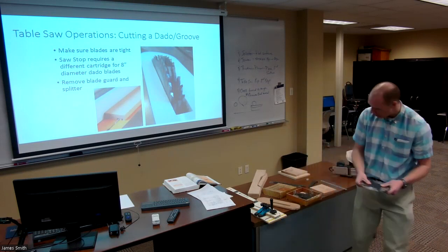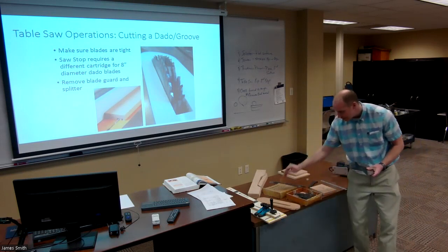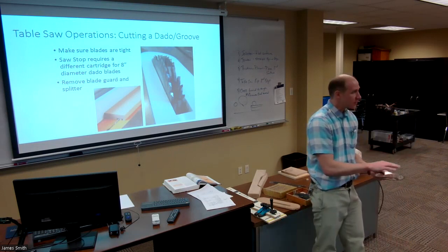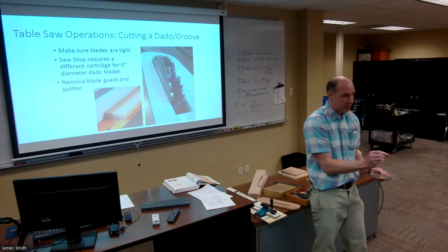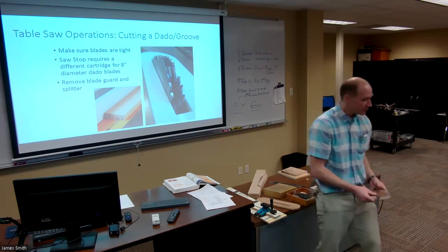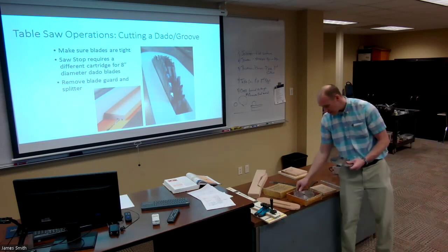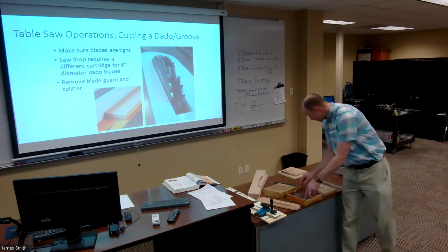And when you need to adjust it, you can use pieces of shim material to stick in between the stack, and now you just need the 16th or 64th or 32nd. So you can add shims to that. And so that's what a dado stack is.